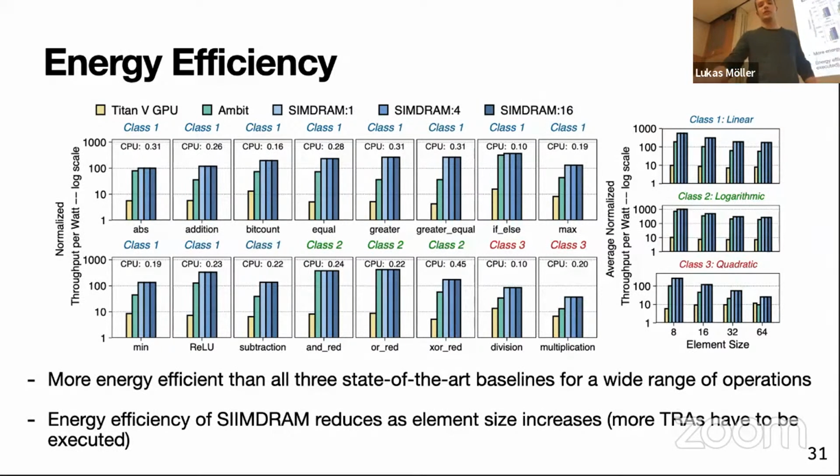We don't have to load data into the CPU because we are directly operating on memory. And we can exploit the abundant memory bandwidth, which we are not using otherwise. In comparison to Ambit, we are reducing the number of required triple row activations by leveraging the optimized majority-based implementation, which is using the 3-step process we saw earlier.